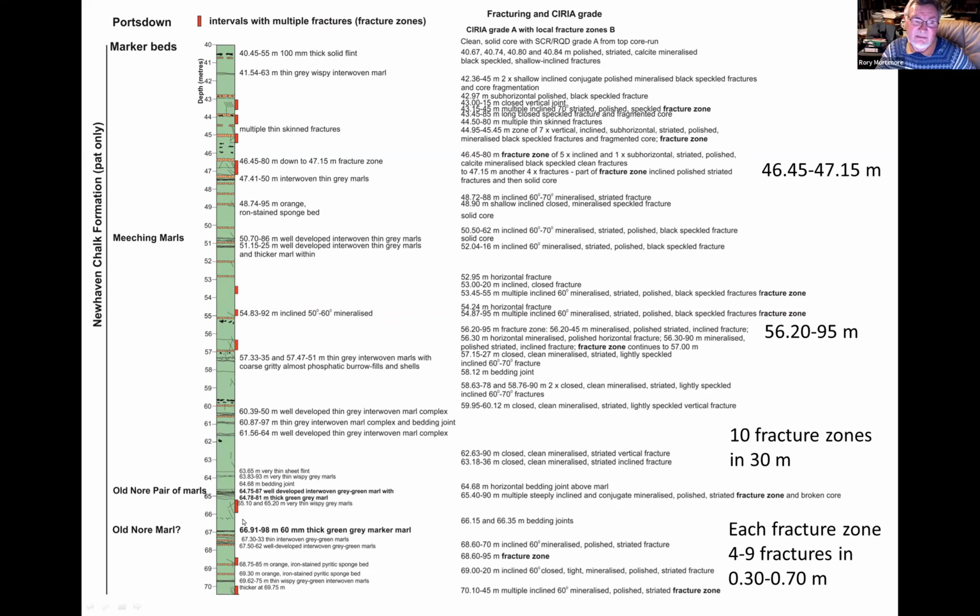And it isn't in every part of the chalk that you get this, but there are some areas of the chalk downland where you're getting these intense fracture zones, and those intense fracture zones will be enhanced permeability horizons. There will be enhanced instability horizons in slopes and tunnels. So actually picking these out over and above your normal grades and your normal fracture log, I think is useful.